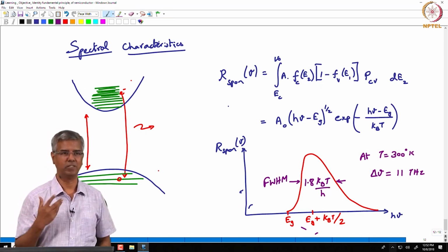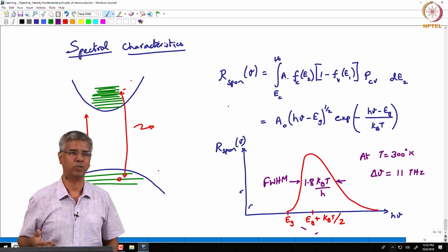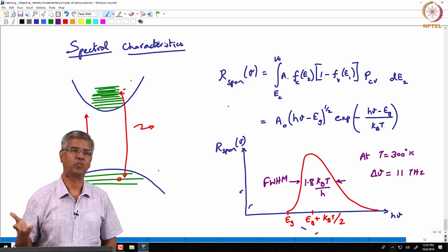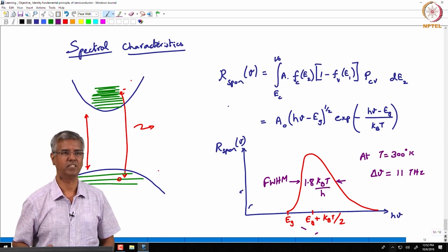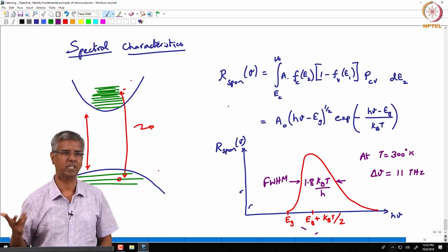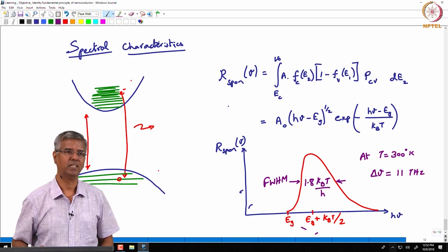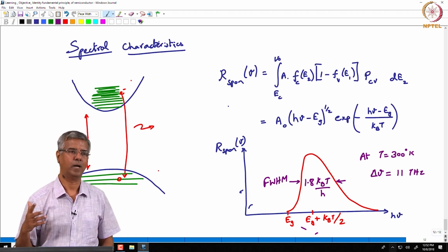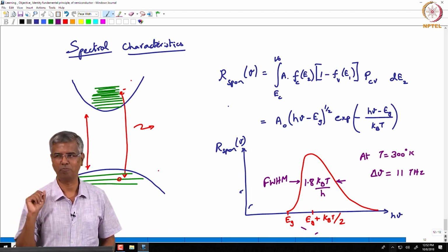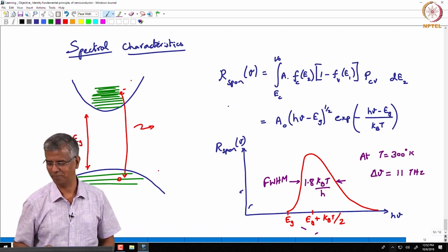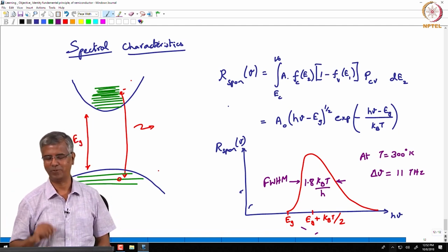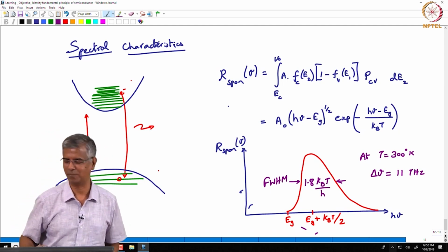So yeah, there is a conversion efficiency involved. There are some photons that could be scattered and not really going through that conversion. So there is a conversion efficiency involved, but I believe the conversion efficiency is greater than 50%. But depending upon the thickness of the phosphor coating, you may or may not absorb all the UV radiation. So I'm fairly sure I'm going to see a UV component coming out of this, and I'm actually curious, as you are, to find out how much of that UV component is coming through.